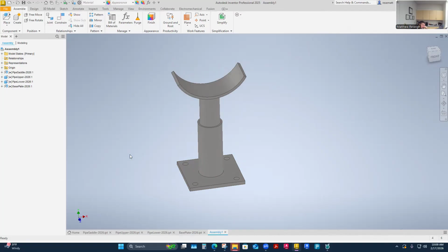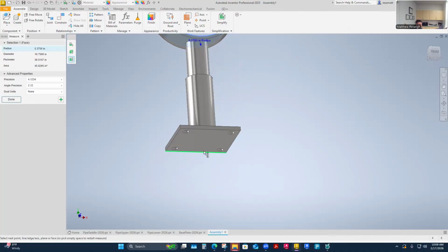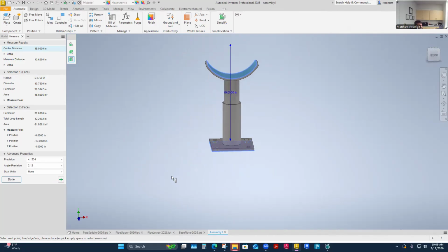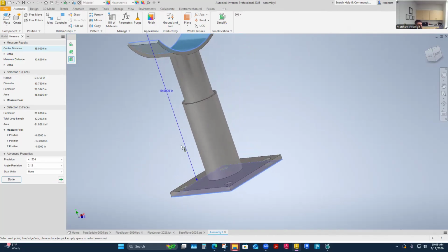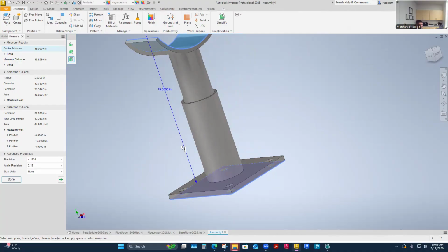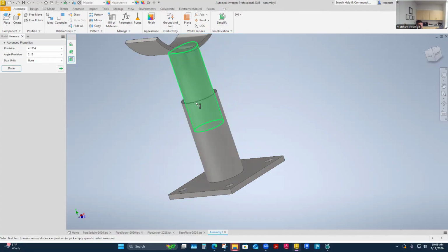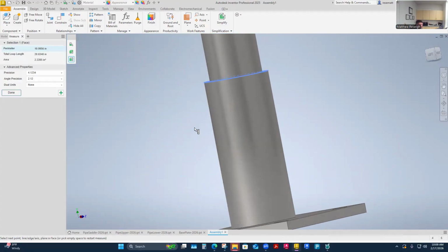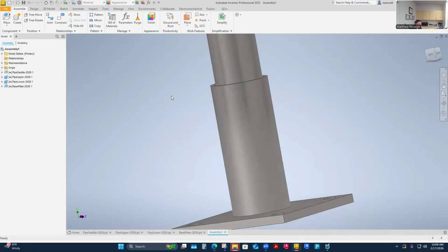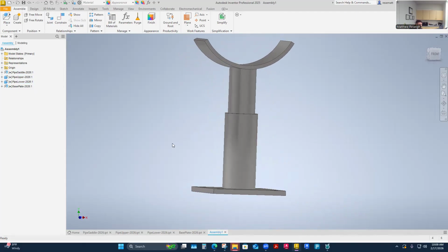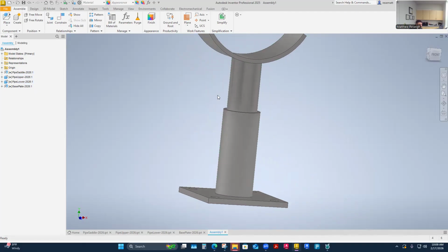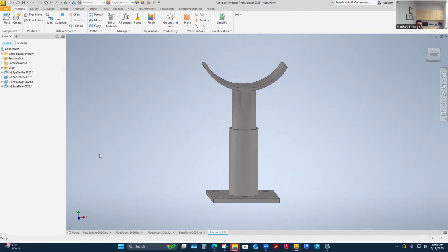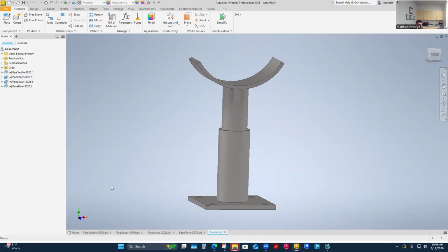Already I can probably get an idea how close I am. Yeah, it's 19 inches, which should be from the center here to the bottom here. So I've actually hit 19 inches at its full length. I think I can even check here. I don't know if I can measure it without making it invisible, but I built it so there's 3 inches of minimum overlap here. And I realize that I can only get as low as 14 and a quarter when this thing bottoms out all the way down. It's going to hit there, I think anyway. I could actually animate that and drive it down as low as it goes. But let's do a drawing.